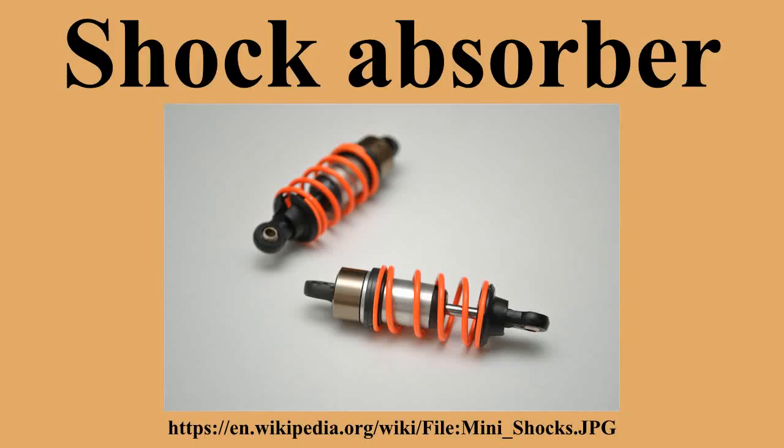One of the problems with motor cars was the large variation in sprung weight between lightly loaded and fully loaded, especially for the rear springs. When heavily loaded, the springs could bottom out, and apart from fitting rubber bump stops, there were attempts to use heavy mainsprings with auxiliary springs to smooth the ride when lightly loaded, which were often called shock absorbers.